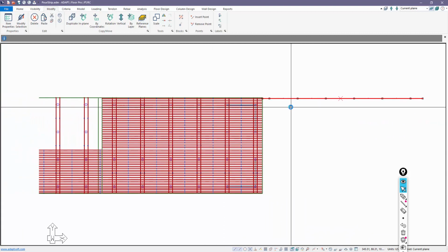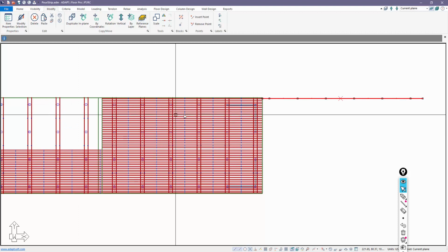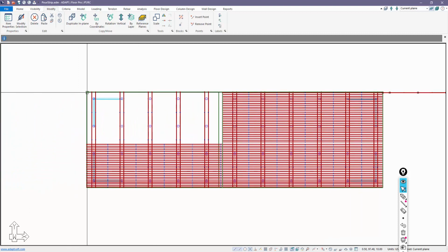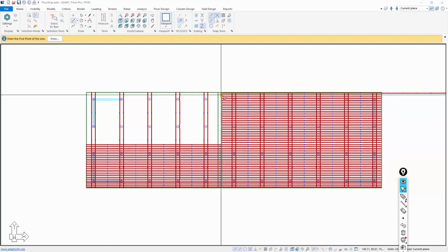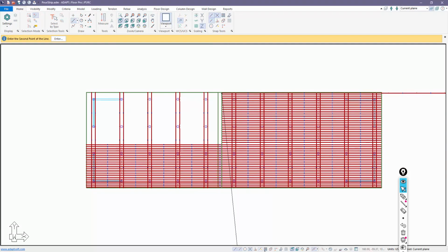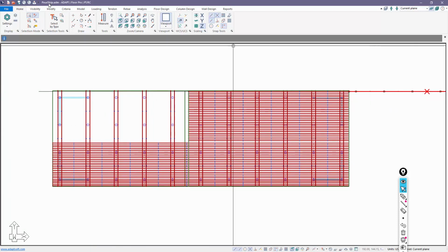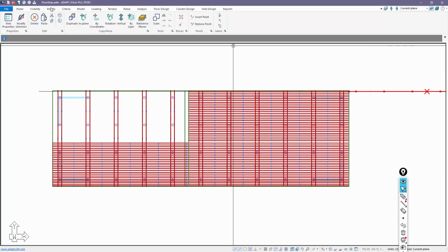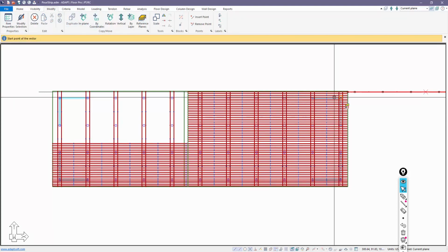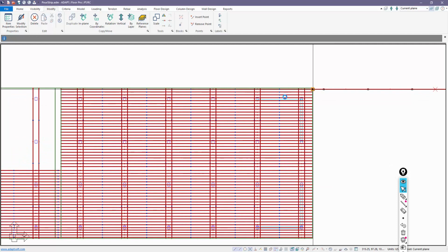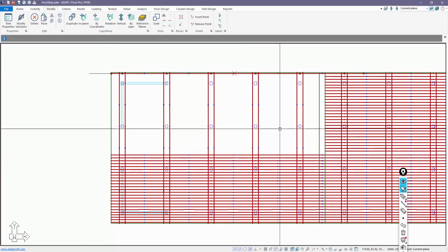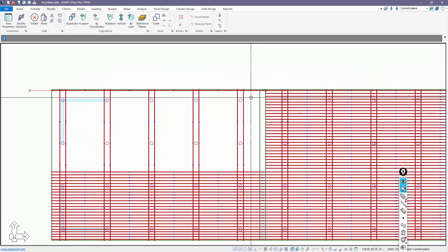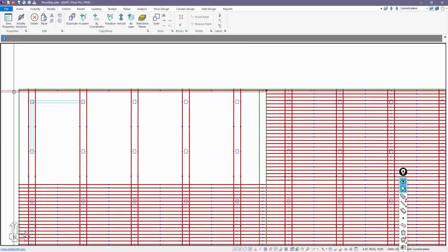Okay, and then I could basically just move that tendon from this point over to a point along this edge. Now, I might need to use a construction line to grab that point. So I can select this point, I can select modify, move in plane, and I can select the base point and then my reference point over here, and we'll say move. Okay, now I need to modify this tendon.